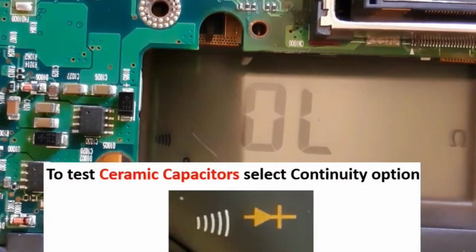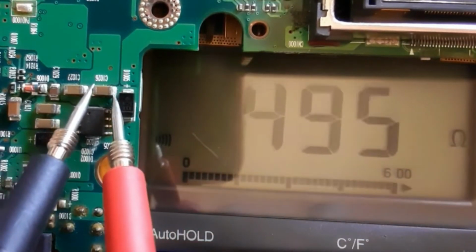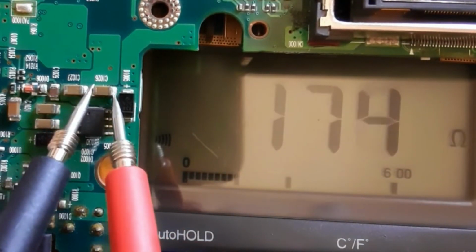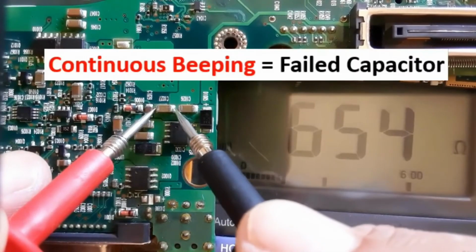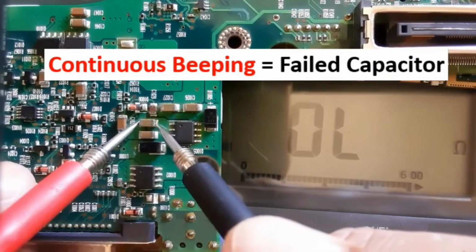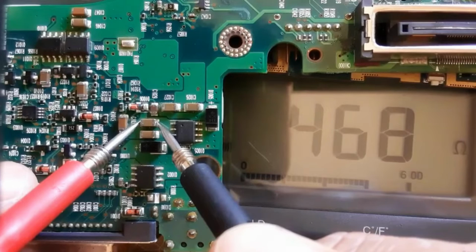Different capacitor types, including ceramic and polarized, necessitate distinct testing methods. Understanding how to test each type guarantees accurate assessments of their condition. A healthy capacitor should display expected values on a multimeter, indicating it functions as intended. Conversely, if continuity or a low value is observed, the capacitor is likely damaged or defective.